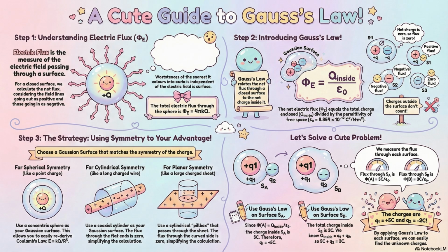It all starts with parasitic elements, doesn't it? It does. Every real capacitor isn't just C. It's an equivalent series circuit with at least 3 other components. Equivalent series resistance, or ESR. Equivalent series inductance, or ESL, and a parallel leakage resistance.